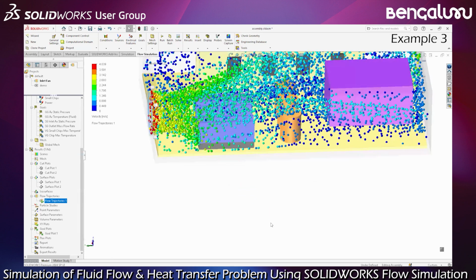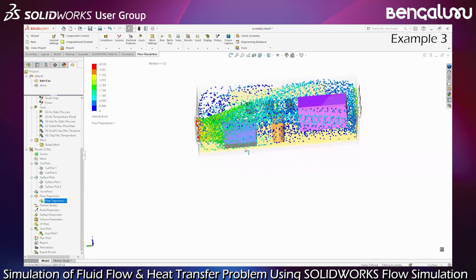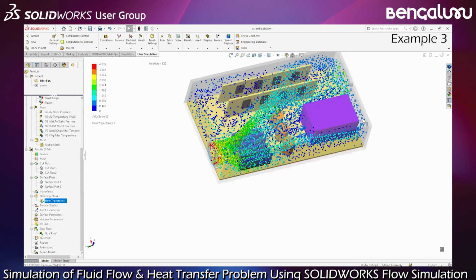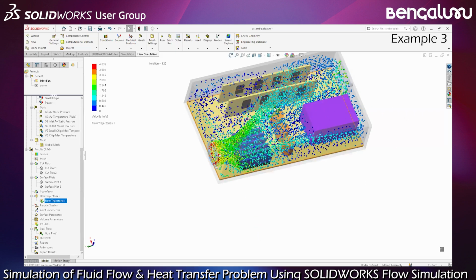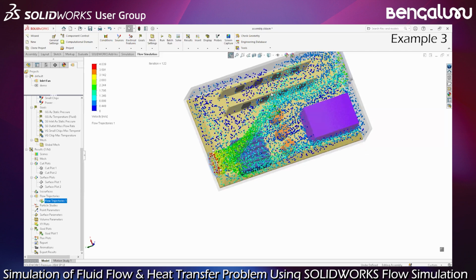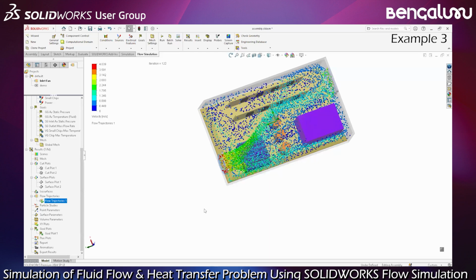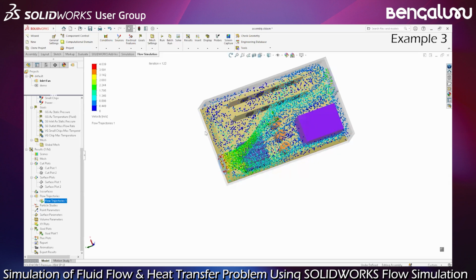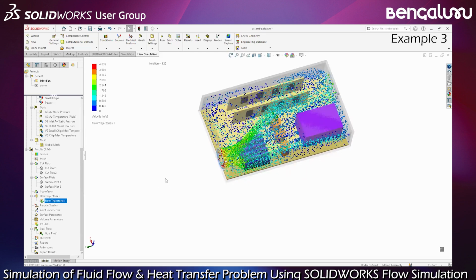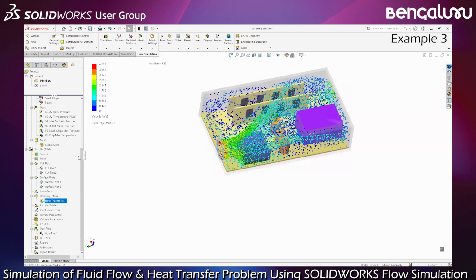Of course, the main component is the chip, and we have to make sure it is well cooled. As well this one, the power, and it looks like there is a small flow here, smaller, but there is something. Of course, maybe we may add another ventilator if needed here or not. So it gives you some information that you can use to modify the design if needed.